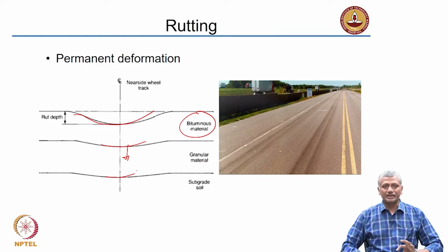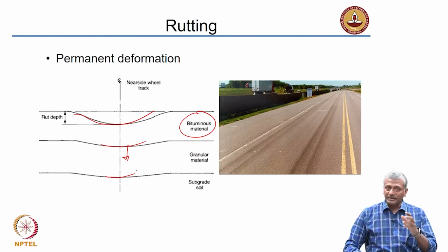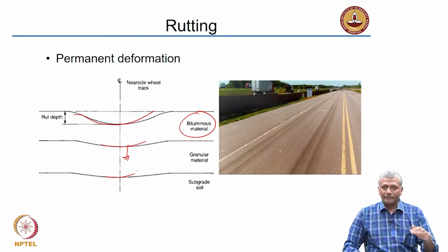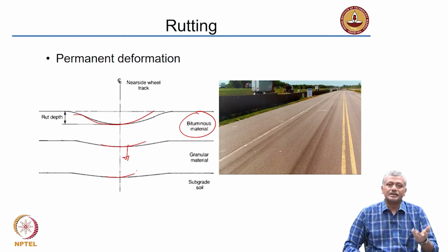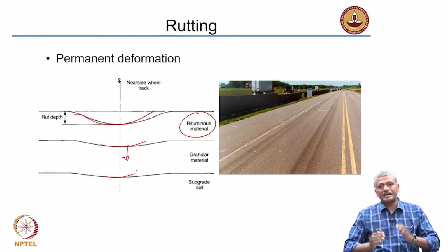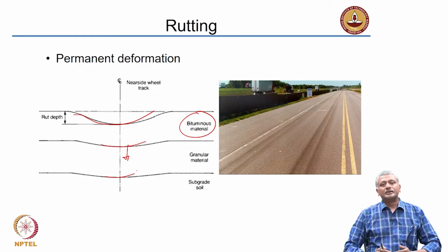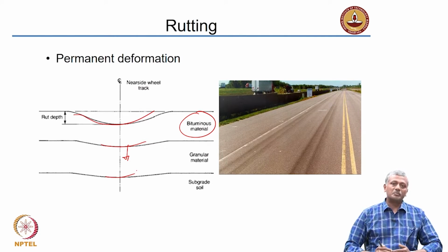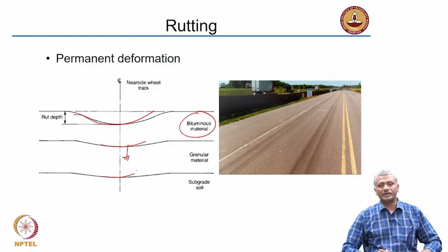Okay. So, you need to ensure that you design the highway pavements with asphalt which is able to sustain the temperatures. Now, one thing you need to understand, asphalt pavements are black. So, in the daytime they are going to absorb more and more heat radiation. As they absorb more heat, the temperature on the road surface will be certainly much higher than the ambient conditions. Sometimes when the ambient conditions are 40 degrees Celsius, the temperature of the asphalt pavement can be as high as 60, right. So, because of this aspect, you need to ensure that you consider not just the ambient conditions, but what could be the temperatures which may happen in the asphalt pavement beyond the ambient conditions and design adequately for that.